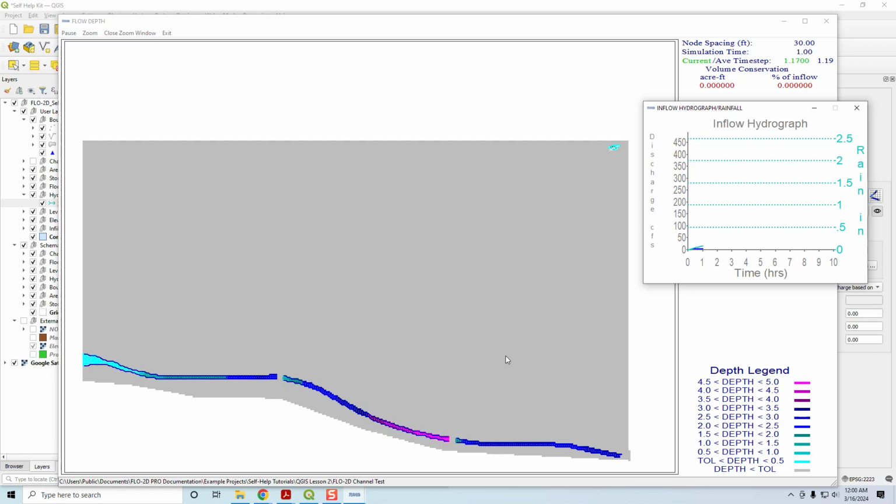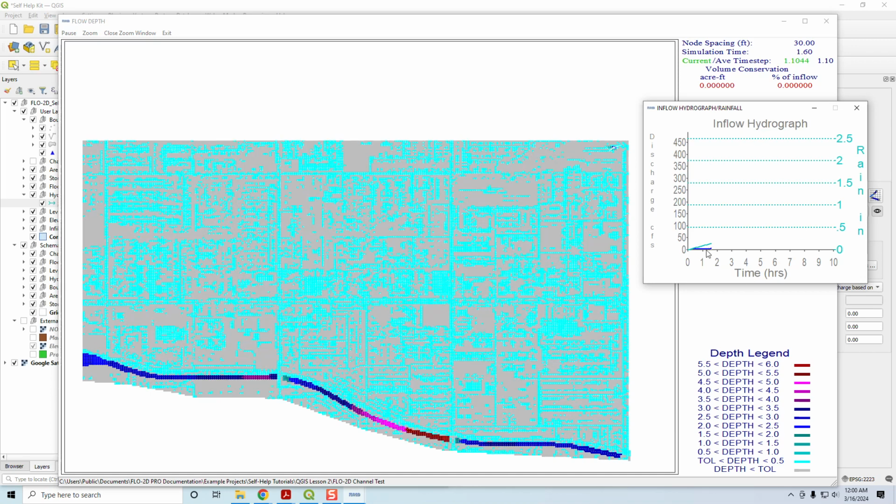So when this simulation ends, we can go into it and see how our water is filling the channel. Now you can see our rainfall is coming up. Oh, I know why we're getting rainfall so early in that channel, because we don't have infiltration turned on, because it's a concrete channel. Okay, that makes sense. So what's going to happen here is that the rain is going to be this cyan color, and then this royal blue color is going to be our inflow hydrograph on our floodplain. So it's going to go up just like this and then come down like that. That'll be our floodplain hydrograph.